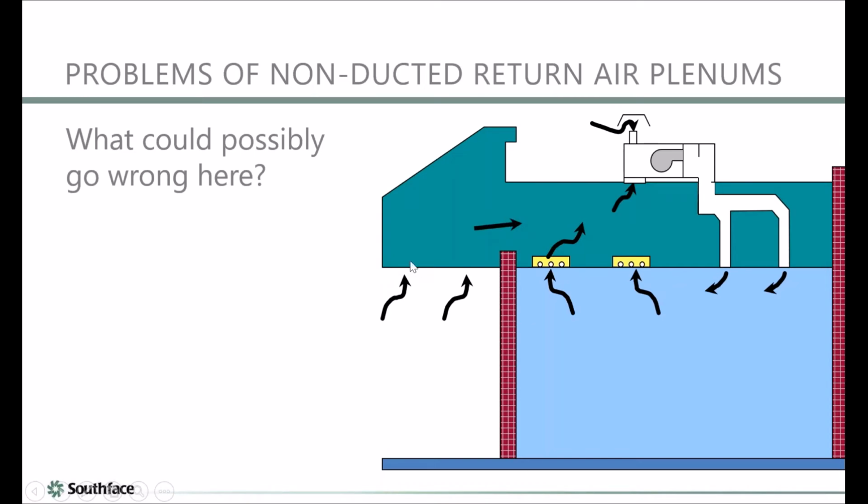So it was already connected because, a lot of times, if the roof is a waffle roof deck and the wall is a steel plate, it doesn't meet, and no one ever sees it. And then it was ironic because on this side there was leakage also, and it connected to an interior space where they were storing car parts and actually working on cars. Oh, wow. So there was a little bit of risk of carbon monoxide and things like that being pulled in. So that was one classic example.